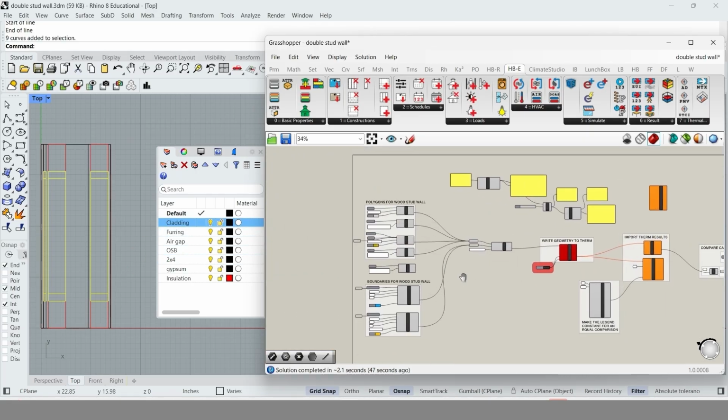As the opposite example, if you forget to set material to one or more of the geometries, the model would not run because it thinks there is a void in the geometry. The void is not vacuum or air kind of void, but rather the computer does not know what to do kind of a void.